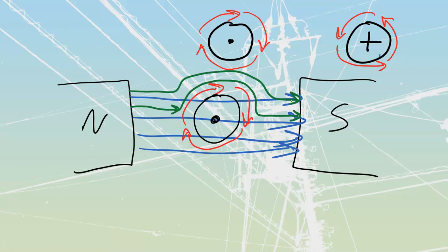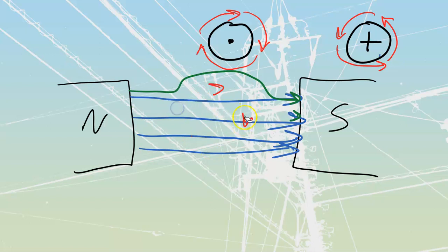What I have created at this point is nothing more than a slingshot, where I have got these lines of force. Remember, they possess elasticity. I've now stretched them back like having a rocket in, which means that what they're going to try to do is expel this current carrying conductor out in that direction. If we were to change the direction of current going through that conductor, just do that real quick.